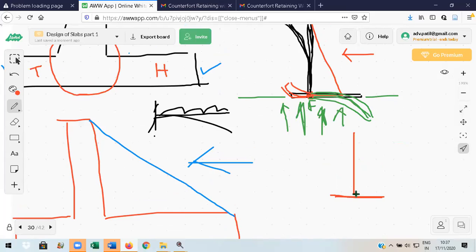Observe here. Now this is what is your... Actually, the shape after bending will be this one, this one, this one. In this way, all these components are cantilever slabs, and they bend like this. Which means if you draw the thickness here like this, and again like this, and again like this, you should understand the position of reinforcement.